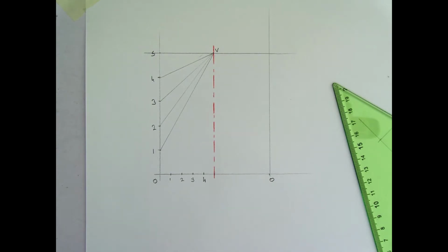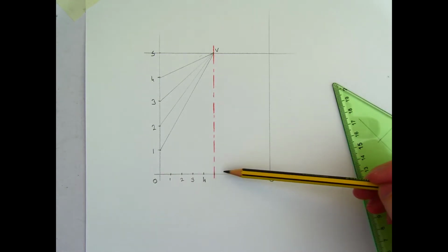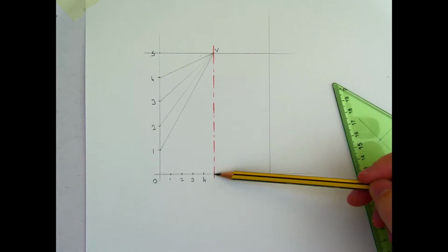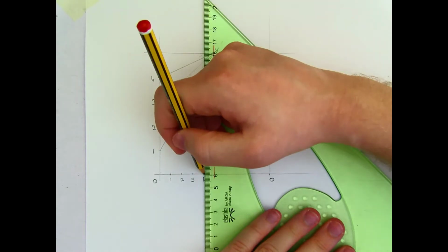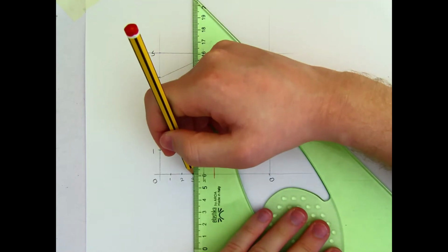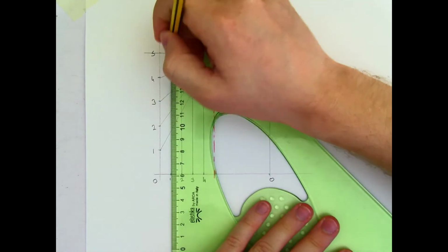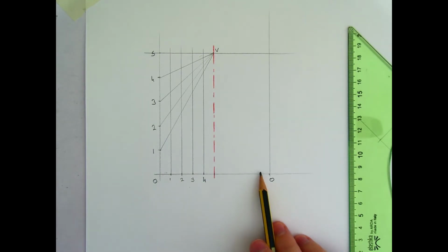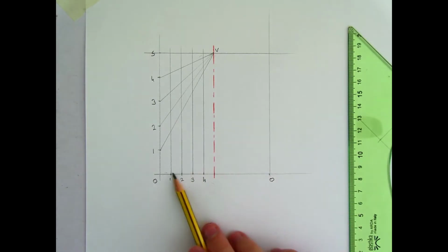Now this is where the confusion comes into it. On the side that is perpendicular to the axis, the lines must be drawn parallel to the axis. So these ones here, they're on the line that intersects with the axis, and they need to be drawn parallel to the axis. This is where our confusion arises. The ones that intersect the bottom edge of the rectangle, the ones that intersect the axis, need to be drawn parallel to the axis.